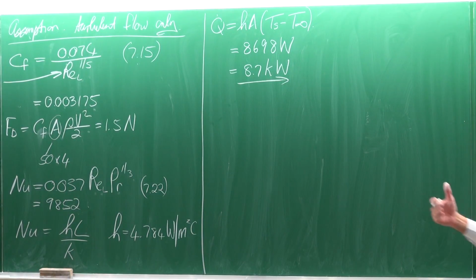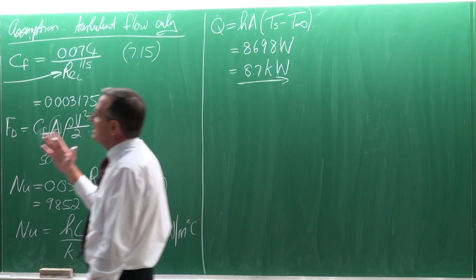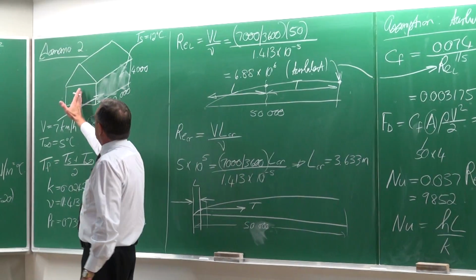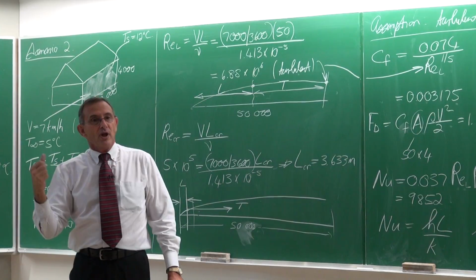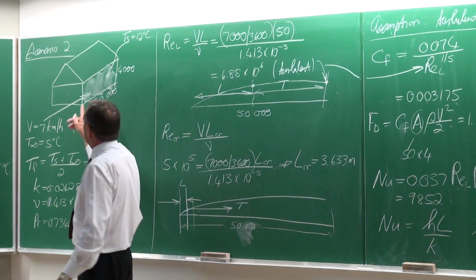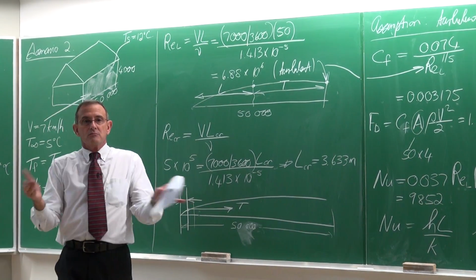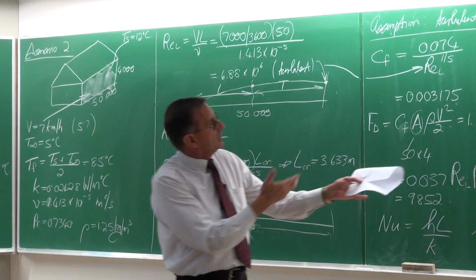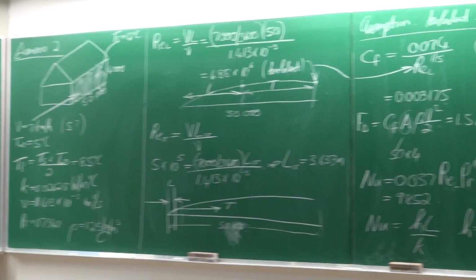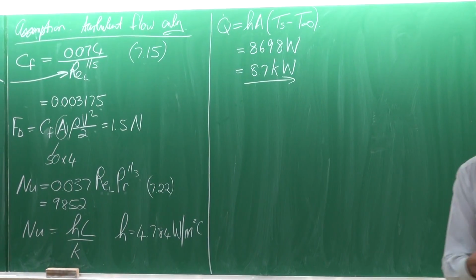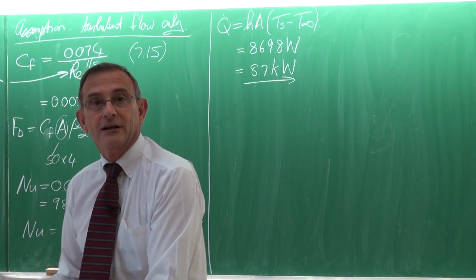So, the air conditioning system or the heating system in this house, just because of the heat transfer rate through that one wall, would require about 9 kilowatts of heating for this one and for that one. So you can multiply it and you can get approximately 18 kilowatts of heating required only for the two walls, the long walls. Right, do you understand?